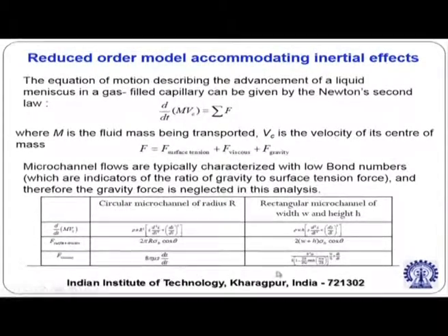The viscous force for a rectangular microchannel, we have solved the problem of flow through a rectangular microchannel, the exact analytical solution. From that you can calculate the viscous force, it will come out to be in the form of this tan hyperbolic form which is given in this slide. Parallel plate channel is a special case. Here we are talking about the rectangular channel where none of the width and height is negligible as compared to the other, or too large or too small. But if one of the dimensions is much smaller as compared to the other, it effectively becomes a parallel plate channel. But the expression written in this slide is for a rectangular microchannel.